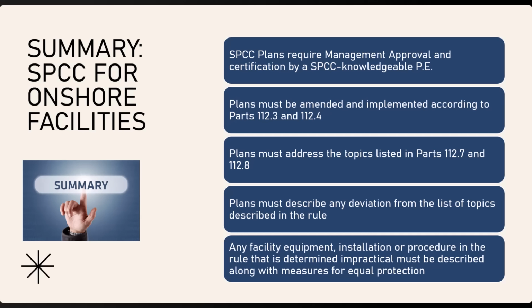To summarize this section on the standard non-qualified SPCC plans for onshore oil storage facilities, SPCC plans require management approval and certification by an SPCC knowledgeable PE. Plans must be amended and implemented according to Parts 112.3 and 112.4. Plans must address the topics listed in Parts 112.7 and 112.8.